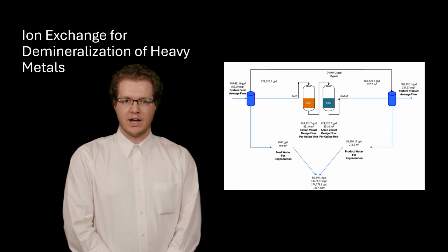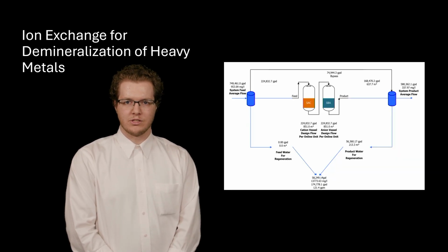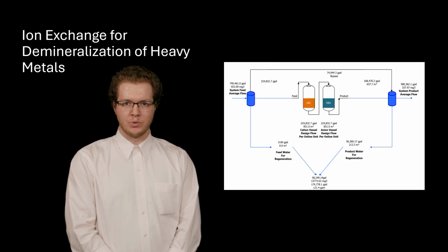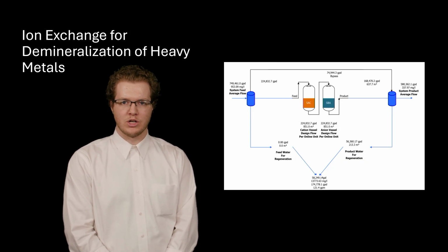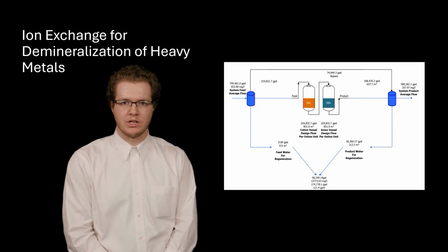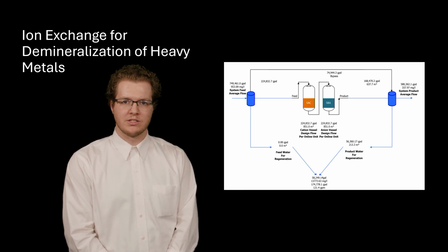Heavy metals often have high heat capacities and low heat transfer coefficients, making them inefficient for absorbing and quickly releasing energy. This is undesirable in cooling towers. Removing these heavy metals requires both highly charged cationic and anionic resin compounds. This approach captures a wide range of heavily charged particles during the cleaning process while leaving other potential contaminants unaffected, helping to prevent scaling over time.